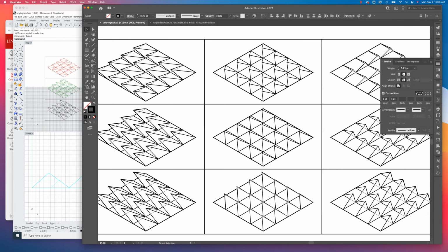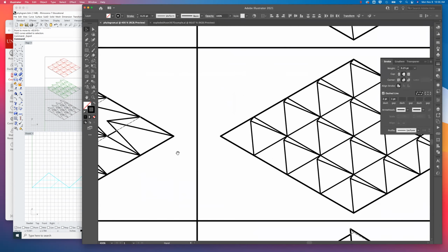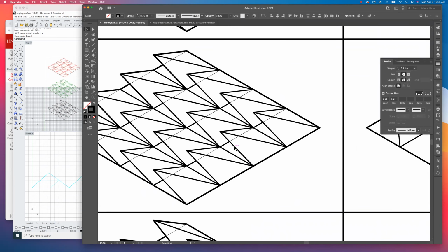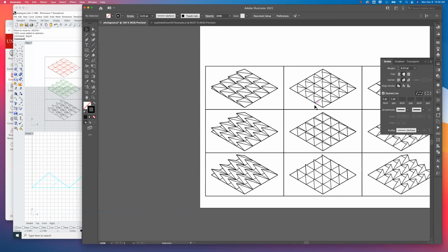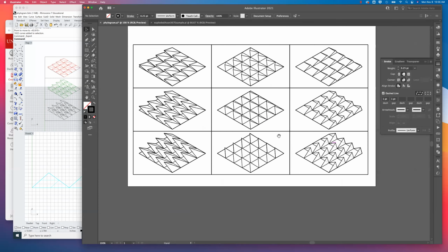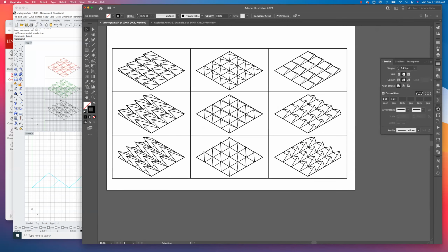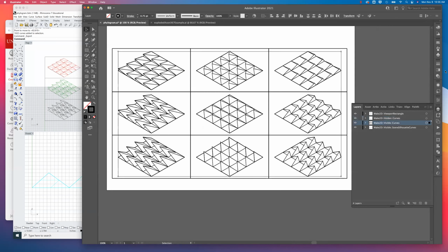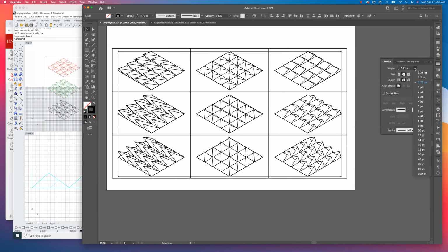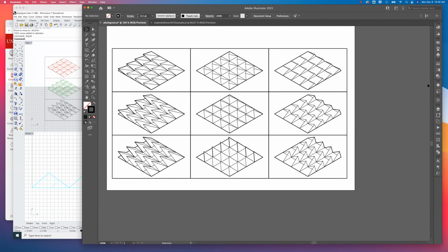You can see I've actually kept the hidden lines on. I've turned them to a line weight of 0.25. And I've given them a 2.1 point dash gap. So 2, 1, 2, 1. I could do that 1, 1, right? Make them a little more dense, a little less dense, however you want each time. Visible curves, let's see, I gave that a 0.75 line weight, maybe I'll do 0.5.